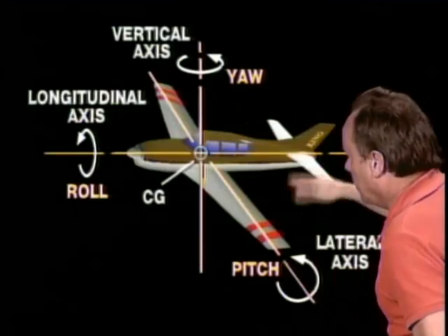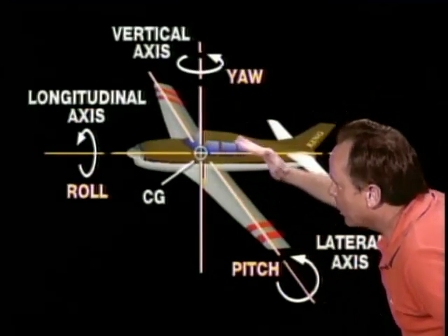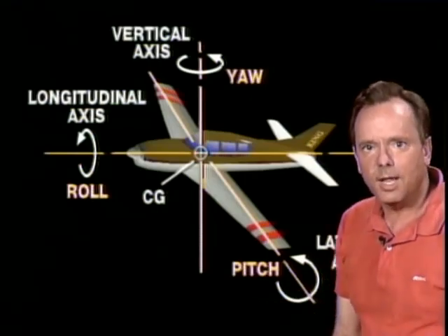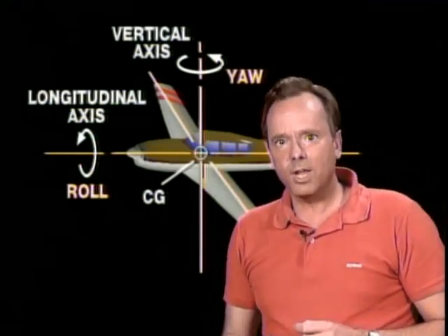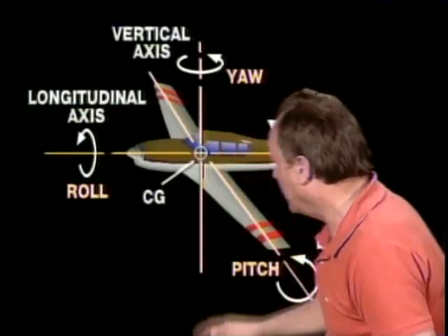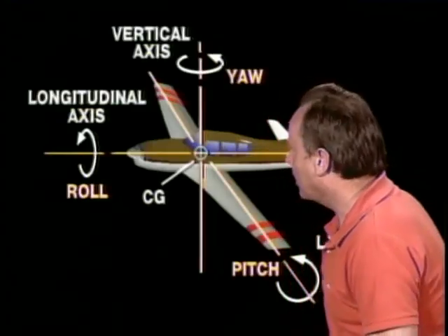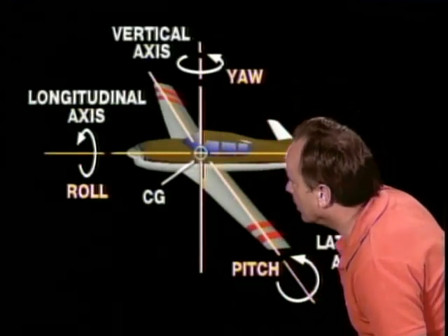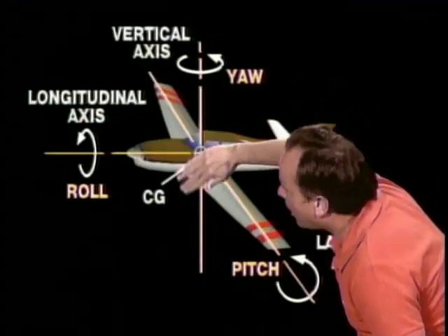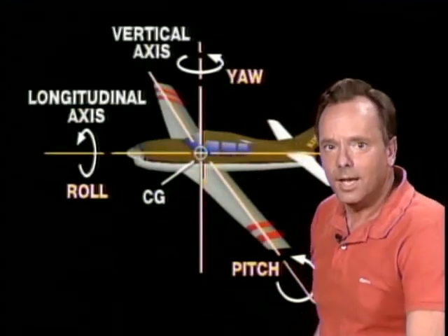So the lateral axis is what the airplane pitches about, and that's what improper rigging of the elevator trim tab system would affect: the balance of the airplane about its lateral axis. Now, if they talked about along the longitudinal axis, they'd be talking about along this line, but it's about the lateral axis. Now let's talk about wing twist and washing in and out of wings, and we're talking